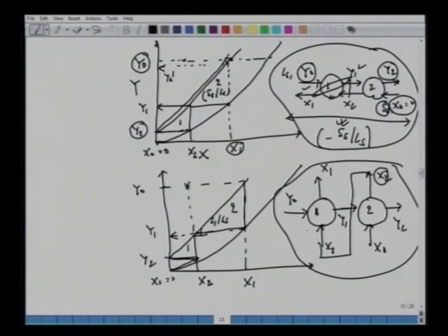Now you take a negative slope for cross current. For counter current we have SS over LS, and for this cross current, if you recall from a stoichiometry balance or a species balance, you can draw the slope with the line as SS over LS, except this is now negative. And similarly here we can have this x2, and we can draw the second slope of the curve as SS over LS. The amount of solvent is the same as the previous case.